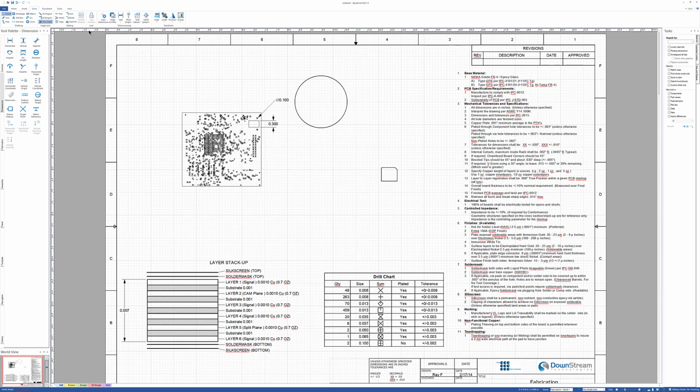Okay. We also have point-to-point dimensioning. Again, I will go to the draw ribbon for this and say add horizontal, and I'll go in here and you'll see the little snap symbol that it's snapping to the center. And I'll grab something else and I'll just pull that dimension off. And there's vertical, lined, angular, and arcs in there. We also have datum dimensioning, which is probably what most of you will use. You can come down here and put a datum down. And then you can start adding dimensions based off of that datum.